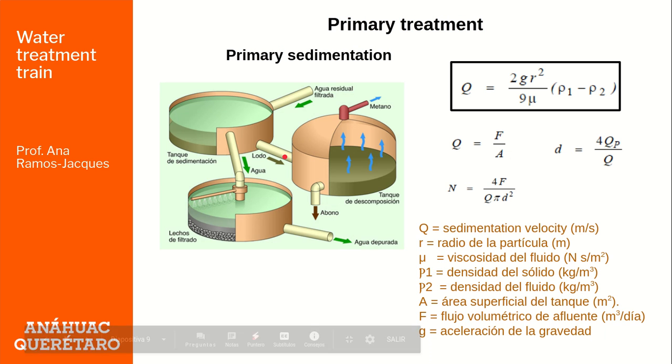You obtain the filtered wastewater here, and then you have a second sedimentation tank, the sludge, and then the treatment for the sludge, and the liquid part is obtained as the effluent water, and in the sludge treatment you also obtain some gases that could be used in other parts of the plant.